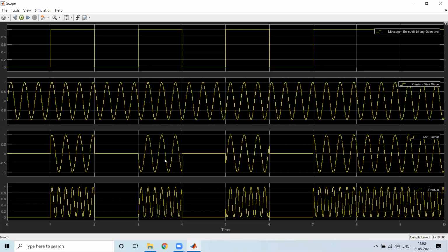When you do this, what is actually happening? If you look at the amplitude and consider all the negative terms, negative multiplied with negative will be a positive value. Positive multiplied with positive is positive, and negative multiplied with negative is also positive. Based on the multiplication, you are identifying whether the carrier signal is present or not. If you multiply 0 with anything, you get 0. But when there is a signal present and you multiply it with the carrier signal, you get some values. So indirectly you are trying to implement the demodulator part.